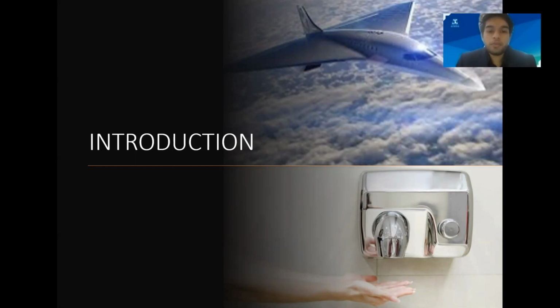A large contribution to ensuring high efficiency is in minimizing aerodynamic losses, which are mainly driven by the interaction of the flow with the blades. The overall loss generated by a compressor blade can be inferred from the wake profile measured downstream of the trailing edge of the blade. To simplify such measurements, static blades are used rather than rotating blades.